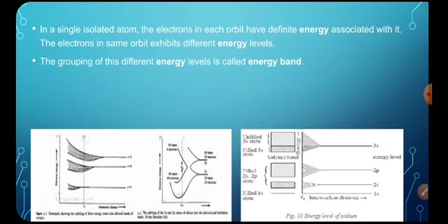Consider silicon or germanium crystals. They contain n number of atoms. Electrons of each atom will have discrete energies in different orbitals. These energy levels will be the same if all the atoms are isolated, that is, separated from each other by large distances. However, in a crystal, the atoms are close to each other. Therefore, the electrons interact with each other and also with the neighboring atom cores.